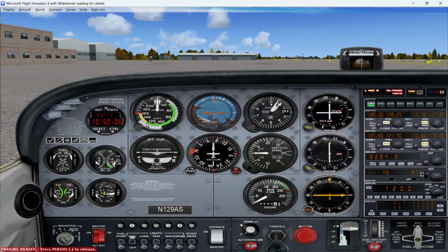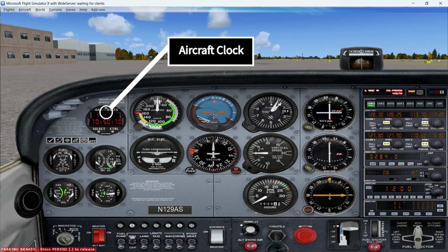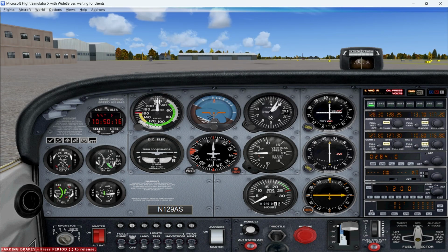which is going to be the aircraft's clock, which is also called a chronometer. It is an FAA-approved time indicator and is required in the cockpit of all IFR-certified aircraft. Pilots use a clock during flight to time maneuvers and for navigational purposes. The clock is usually mounted near the flight instrument group, often near the turn coordinator. It indicates hours, minutes, and seconds.